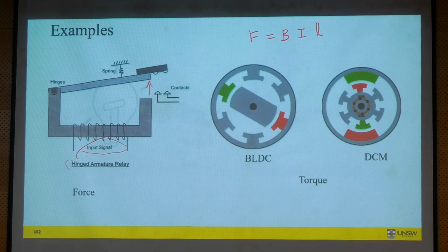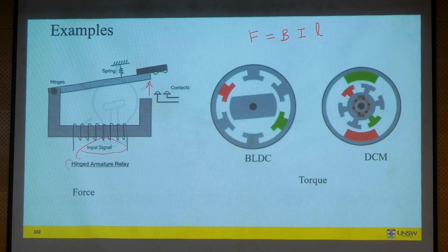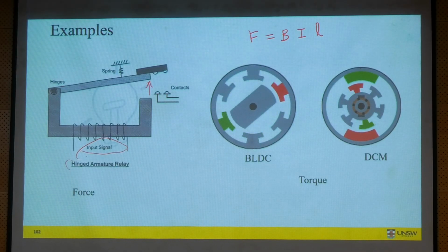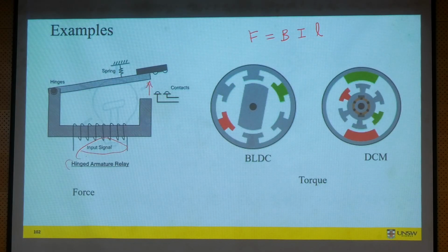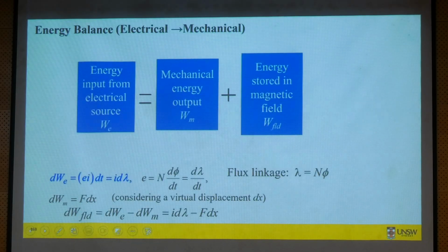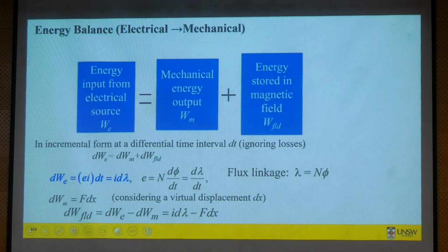But we don't usually use this for AC motors to calculate torque or force. So instead, we start from the energy balance equation, and then we can use the energy to calculate the force or torque using the virtual displacement method, okay?